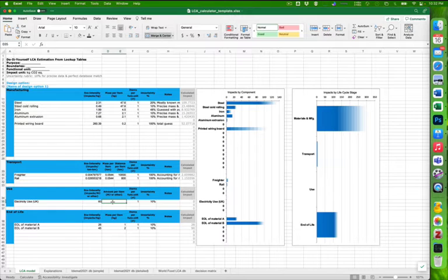So, okay, how do I enter that data? I can either say that the amount per item equals 613.2 kilowatt hours per year, but remember in the database it's megajoules, so I need to multiply this by 3.6 to convert from kilowatt hours to megajoules.